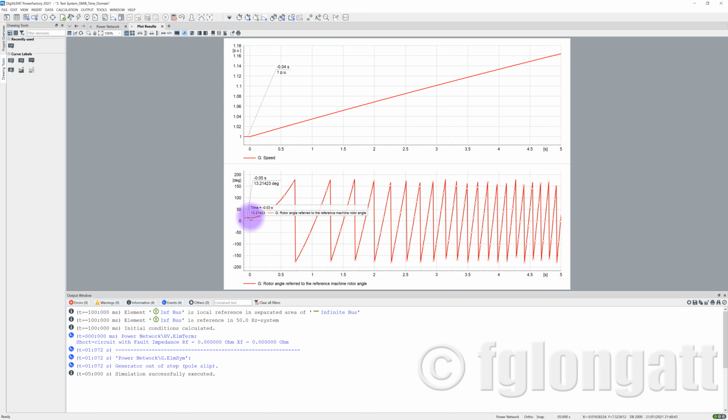You can see over here. Let me follow here, okay? You can see here how the angle, look over here, 19, then 23, then 46, then 124. Oh my goodness. And then reach here, look this number, 178 degrees. And that is 0.72. And then, I don't know if you can see, but here there is a jump. This jump is coming from 180 positive, look over here, to minus 180, roughly. What is happening there is that PowerFactory is creating a plot where the rotor angle is defined between 180 degrees and minus 180 degrees.